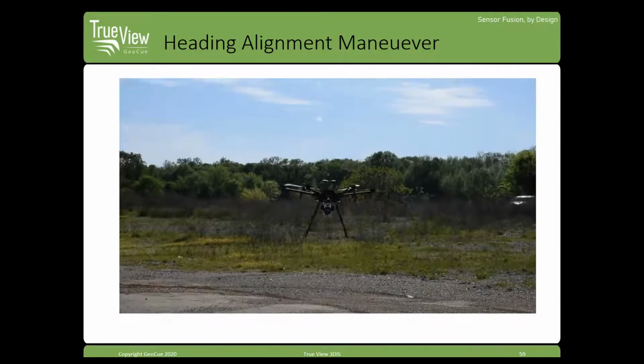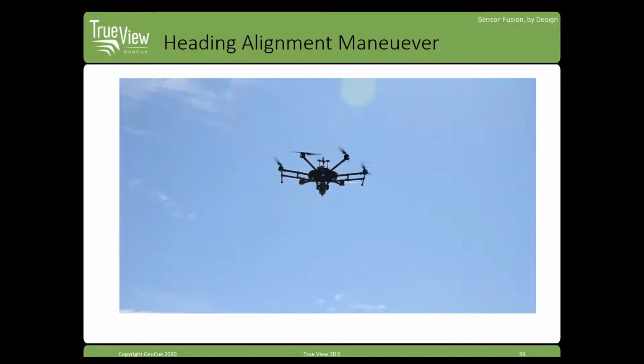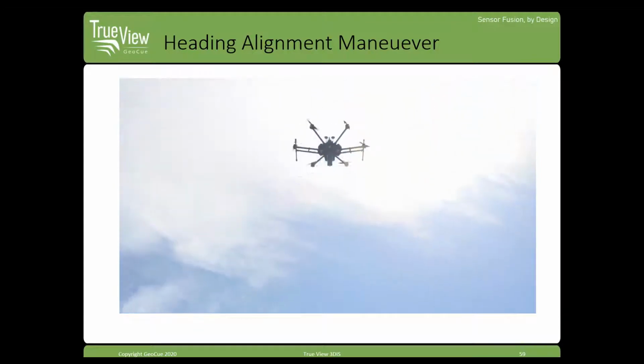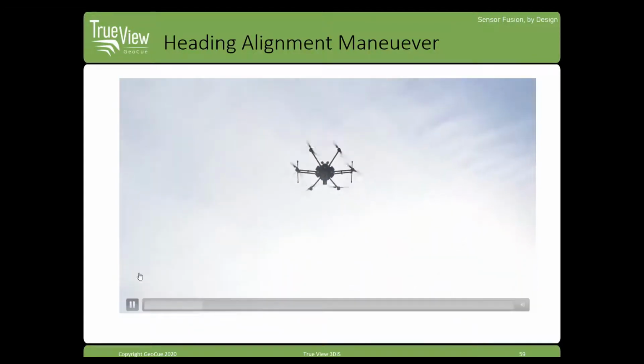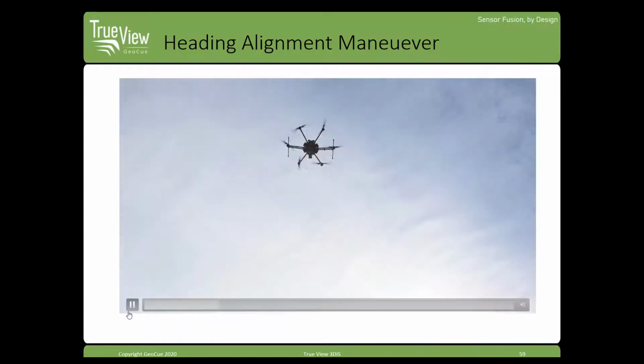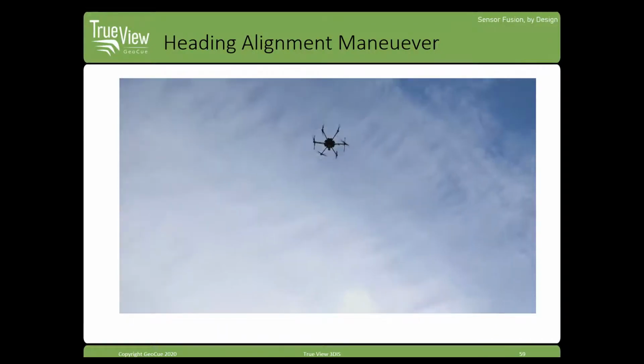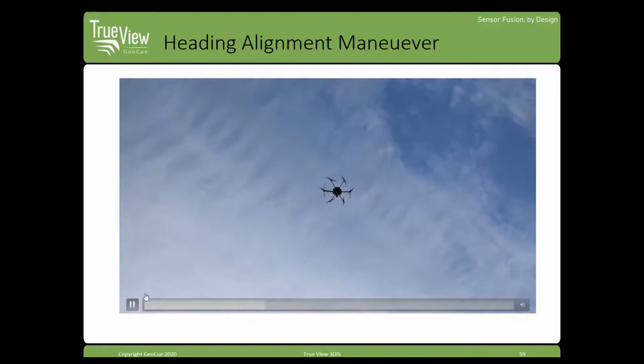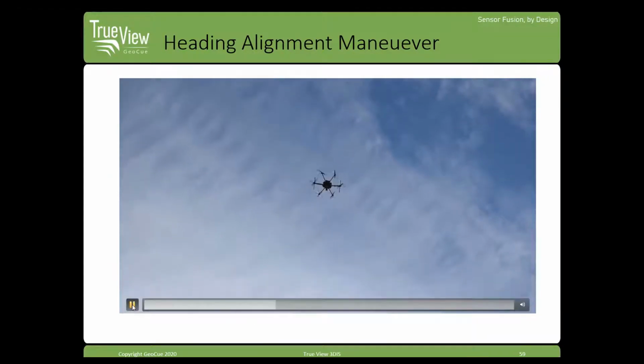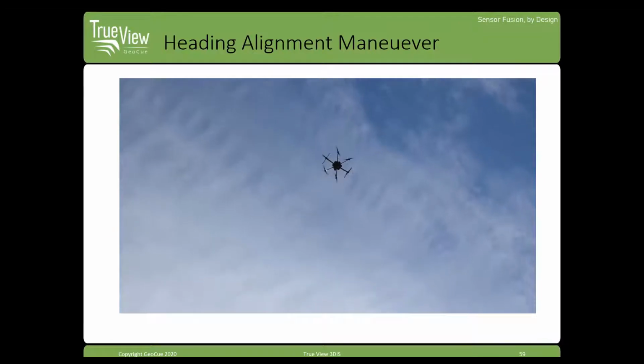I typically go up to my flying altitude. I'll just go straight up. I'll make sure I pick a safe distance to go, or a safe direction to go, over grass. Try not to go over buildings, water, people, whatnot. What you'll then want to do, once you got your safe direction, you'll go full throttle forward.